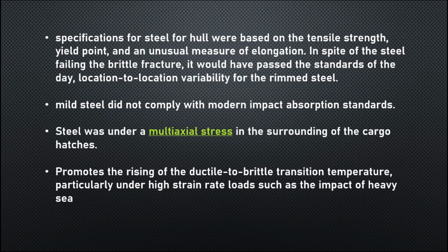The steel was also under multi-axial stress in the surrounding of the cargo hatches. This promotes a rise in the ductile to brittle transition temperature, particularly under high strain rate loads such as the impact of heavy sea.